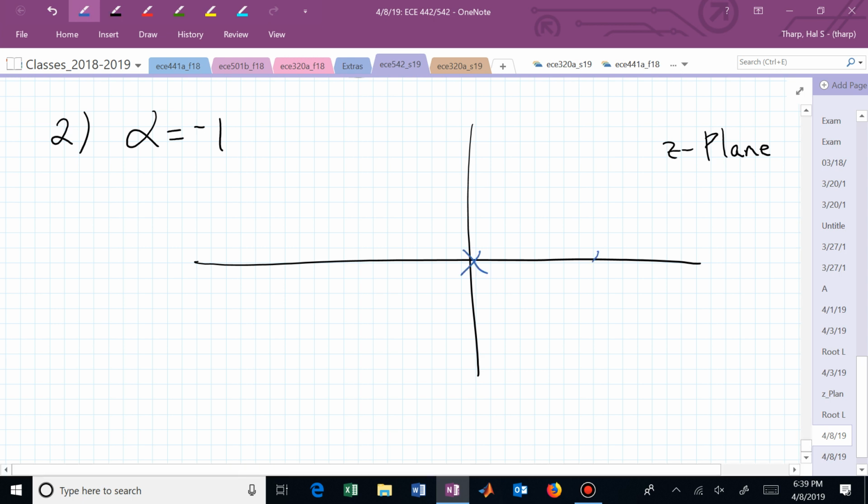Well, we haven't changed where we started. We continue to have that. Now we've placed a 0 where? At minus 1, haven't we? So now we have a 0 over here at minus 1, and now we're in the restaurant. We've got bread, we've got a restaurant. Two poles walk into a restaurant with a 0. But the 0 has to be on a particular location relative to those poles, and now it is. Now we have our design, don't we? Our root locus shape.